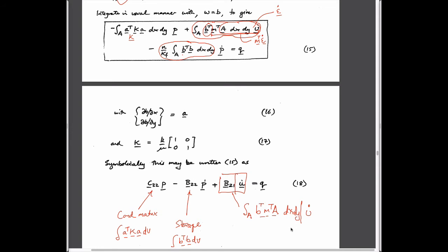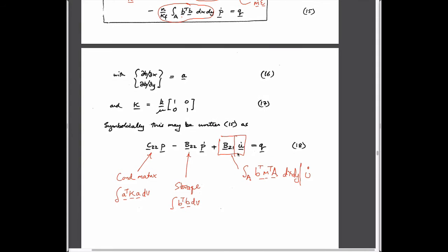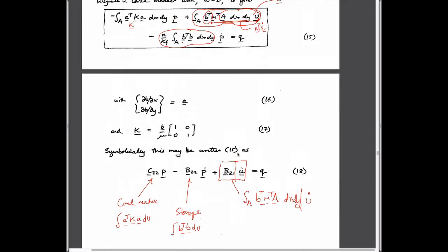So that's it. And so we have a second order PDE for the flow equation, we know that. We have a zeroth order PDE for the capacitance term. And we have a first order equation for the strains, du dx, that squeeze the fluid out of the system. So you can think of it in terms of displacements, which are the nodal variables, but displacements are really representing strains within the system. And so if we take this now and put it back into this previous expression,